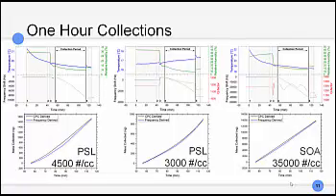And just as a reference, ambient particle concentrations for sizes from 100 nanometers to 3,000 nanometers is on the order of 3,000 particles per cc. So these are very highly elevated levels. But the idea for doing this is that we wanted to know what that saturation limit is. So how long can we run this for before we need to really start worrying about the calibration issues.